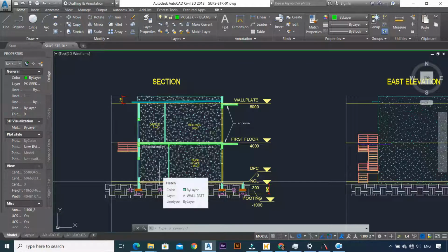And remember, we're using bases because the client specified they wanted a frame structure in case they want to expand, join this to another building, or build to the side. So they want a standalone frame structure that will not result in them having to dig or remove walls or try to upgrade from strip footing to a pad footing.